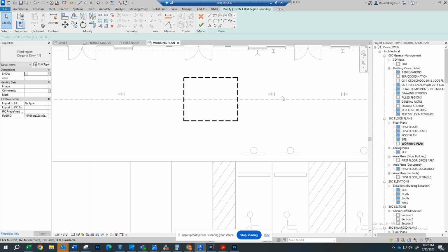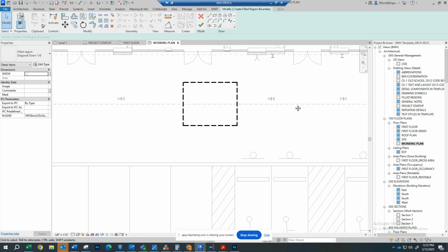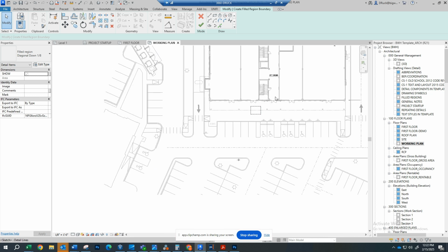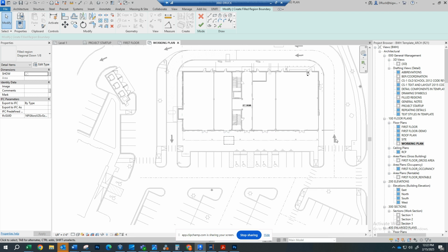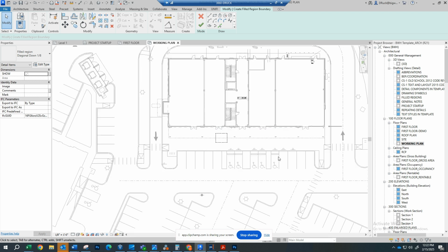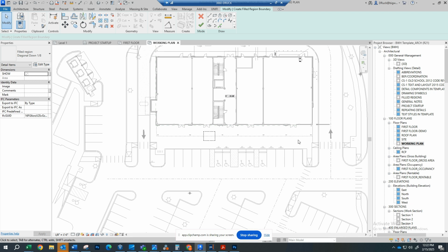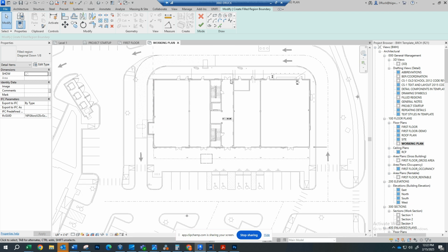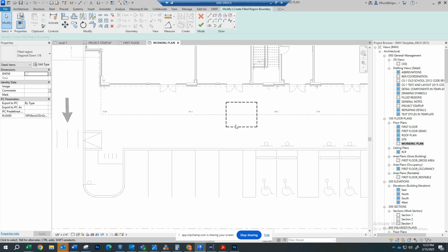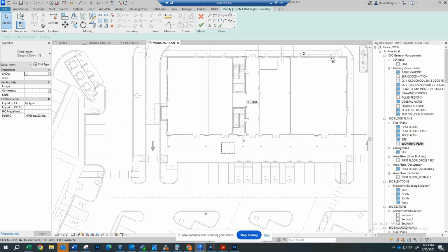So that's something important to note. Like if you're going through and tracing all the way around here, and you're getting towards the end, and then you try and press check, and it's saying there's not a closed loop somewhere. Sometimes this happens, and then you have to spend some additional time trying to find where the closed loops are, or where the opens are.